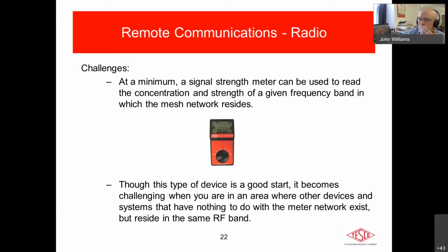One of the things that the mesh networks in particular do, and this is a little bit of a difference why I talk about this device and the meters, the meters themselves, there are some redundancies built into these mesh network protocols where the RF interference that you might see from other devices can be mitigated by a technology called frequency hopping, is a term that's been used.